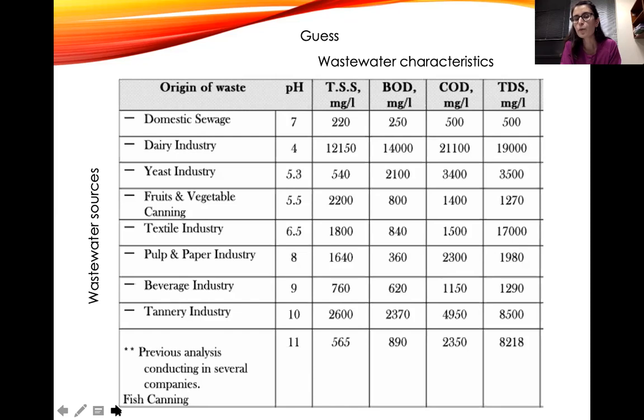So, for example, if the water body requires light and there's a lot of TSS in it, if the microorganisms in there require light, that means the TSS would stop light from getting in. So what would you do? The suspended solids are the ones that cannot settle. If they're big enough, they should technically settle, and then you will take that one out first, and whatever's in suspension, you'll think of ways to treat it.